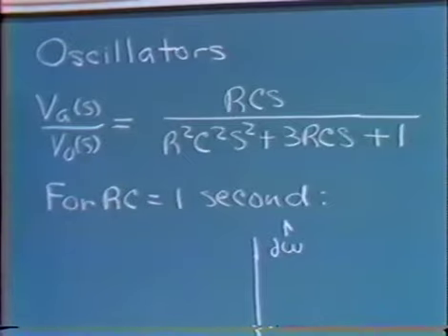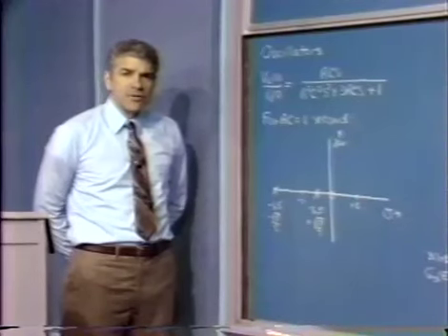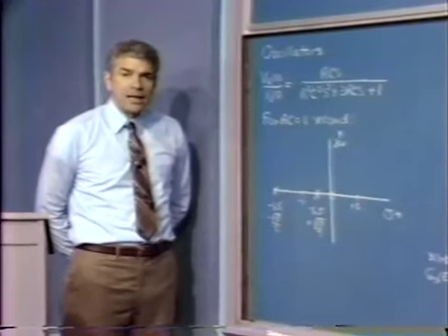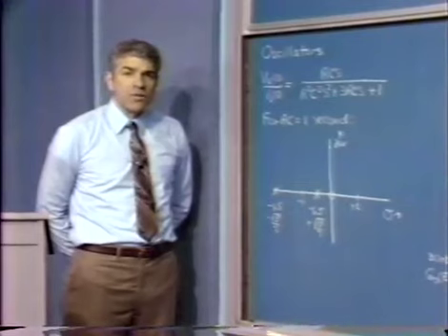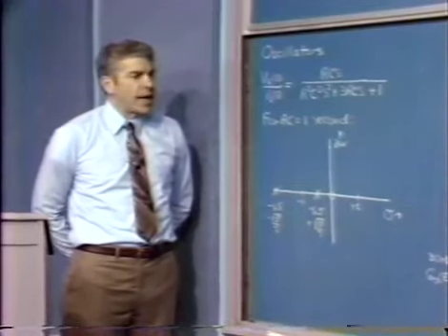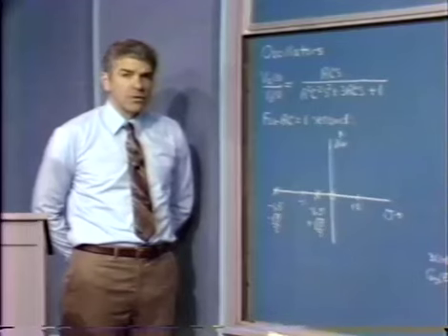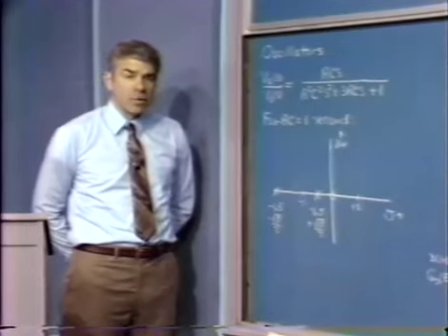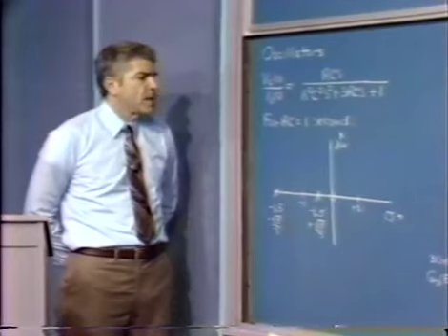So the Wienbridge then gives us positive phase shift at low frequencies, negative phase shift at high frequencies, and at a frequency omega equals 1 over RC, the Wienbridge gives us no phase shift and a magnitude of 1/3 from the input of the Wienbridge to its output.